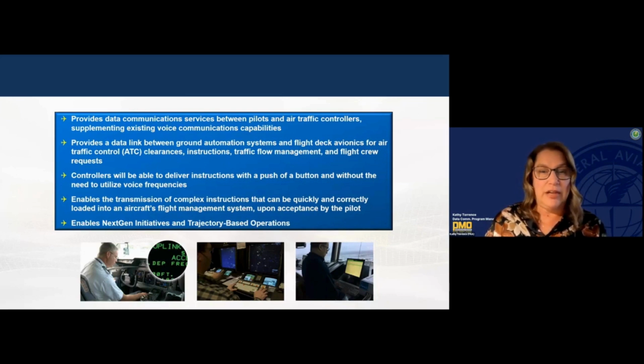We actually have today with FANS the push to load capability already. So we're able to take advantage of those benefits that Anna mentioned are coming in the next segment of CPDLC in Europe. So again, controllers are able to deliver instructions with a push of a button, right, without having to be on frequency. And one of the real benefits that we see, especially with the push to load, is the transmission of complex instructions that can be directly loaded in through the push to load. And that really does save time. We'll talk a little bit about what we're seeing en route. And also from the US perspective, the implementation of Data Comm really provides the foundation for upcoming other NextGen initiatives like TBO and some others as well.